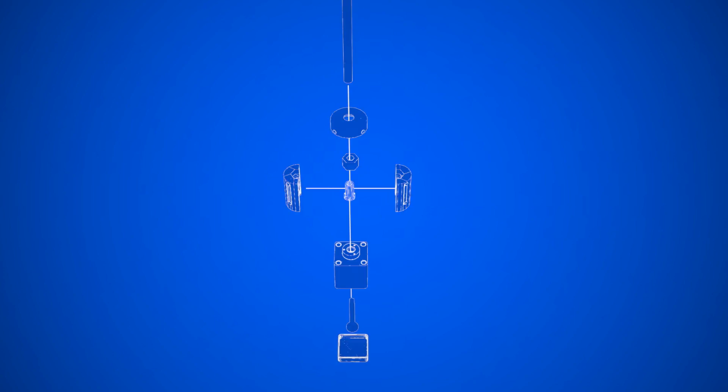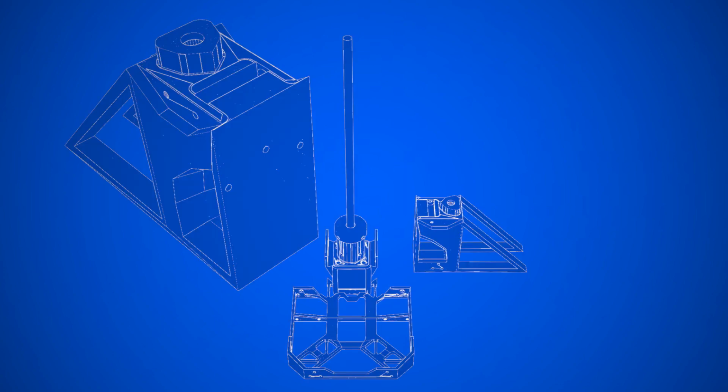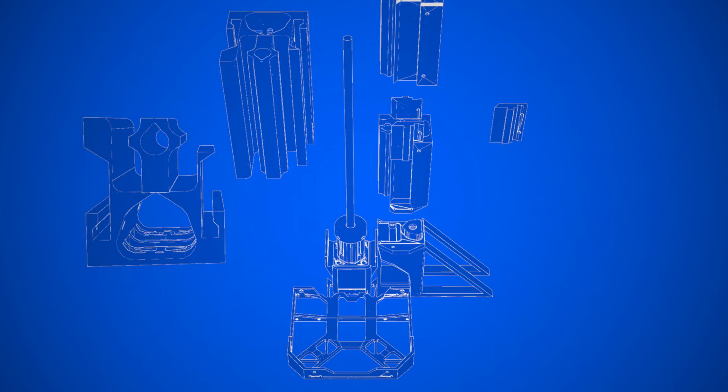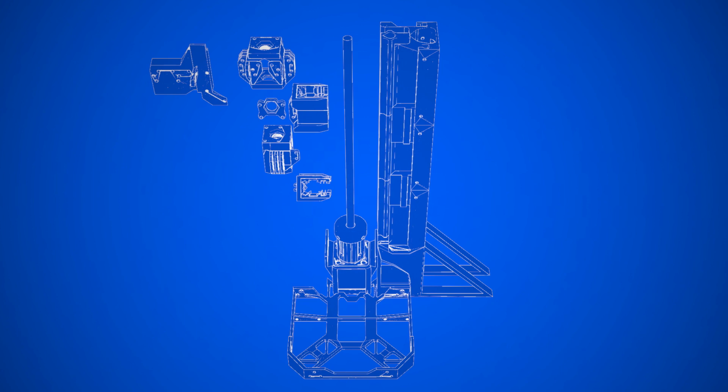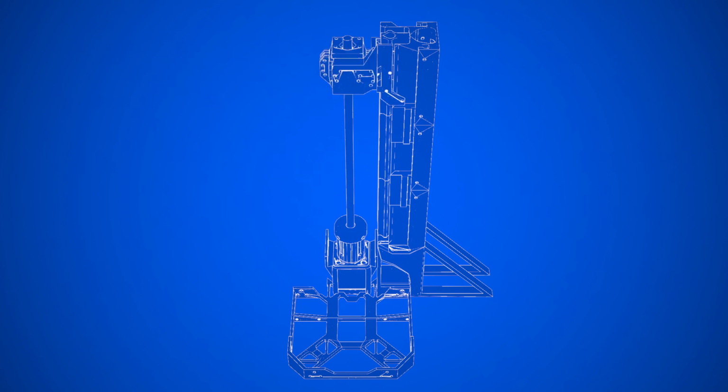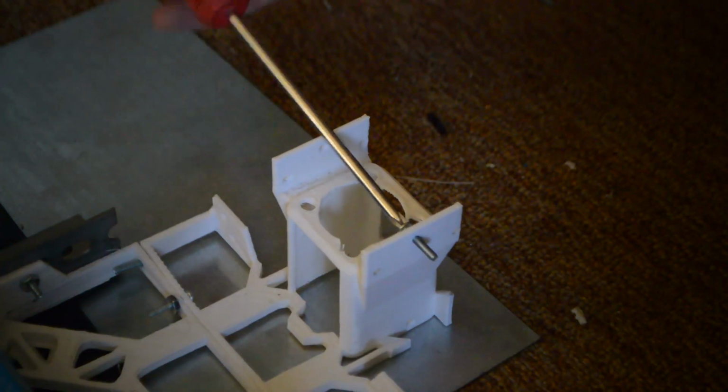Alright, so the next thing that we're going to worry about is the Z-axis. How many 3D printers handle this is just a drill rod with a nut. If you lock the nut in one position and you spin the entire rod, the nut will want to unscrew or screw in, which raises and lowers. So just like I learned from the print bed, I want a linear rail system to hold that nut in place.